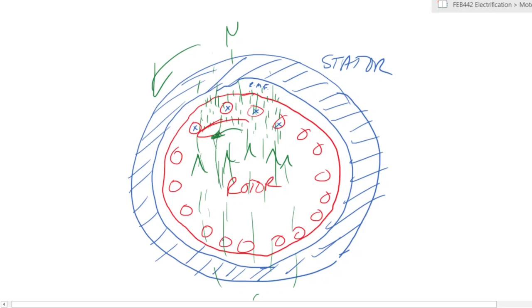And on this opposite end, you would have the windings, because generally the windings would be in the opposite direction. You'd have your force in the direction that is opposite. So the bottom side will see a force in that direction, and the top side will see a force in that direction. And remember, your rotor is mounted on bearings. So what happens? It then begins to rotate in the same direction as the direction of the rotating magnetic field.